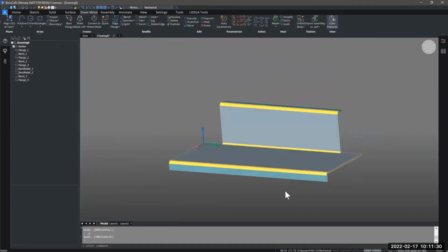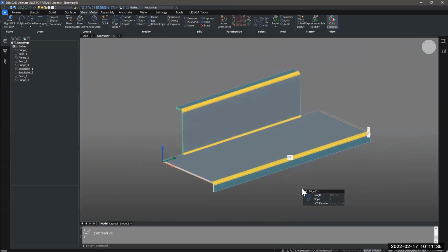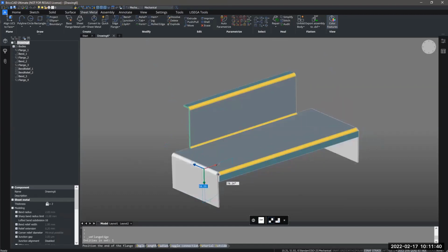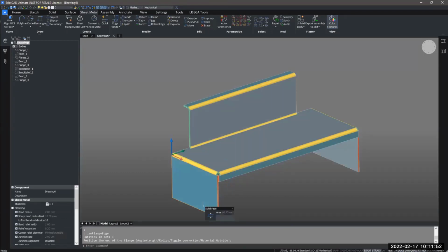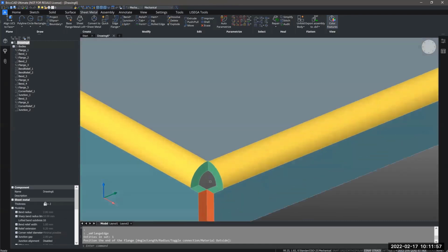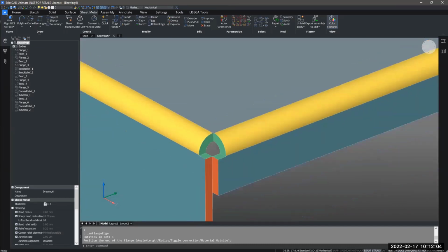So I can select this edge and I can select this edge. You can do it one at a time, but you can also do them both at the same time. Like so, you can see it will make them symmetrical for me. I will take them downwards with a distance of 66 millimeters and 90 degrees. And you can see on the corners here, it has also created these bend reliefs for me, allowing it to be able to be produced in a realistic sense as well.